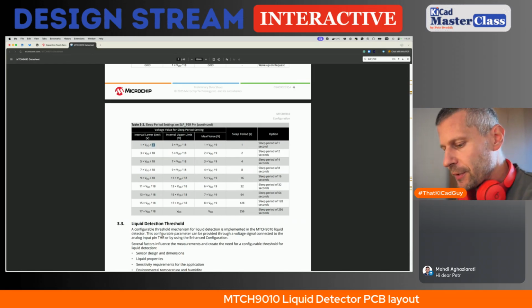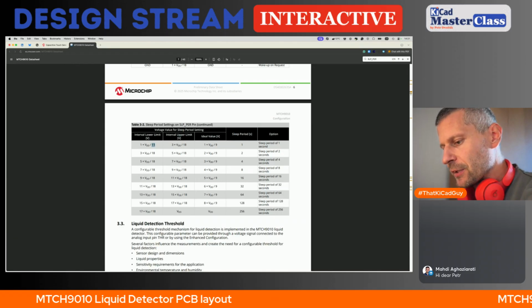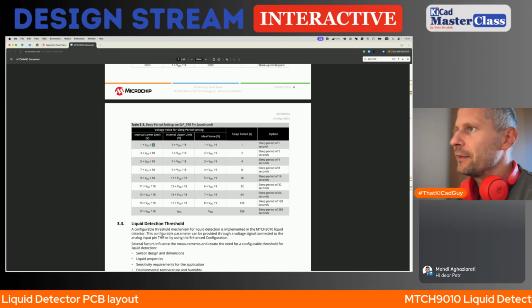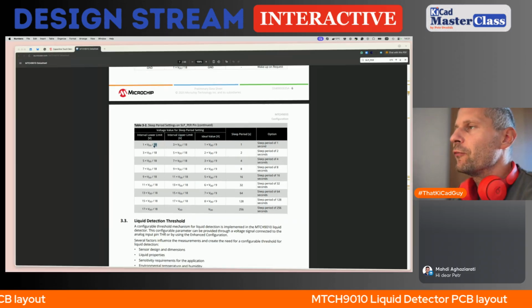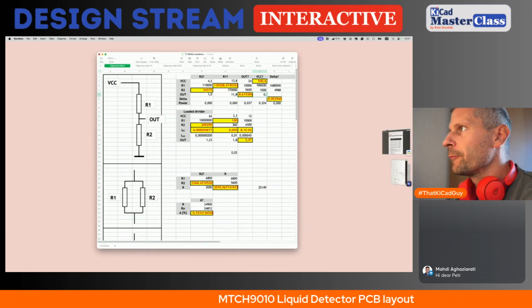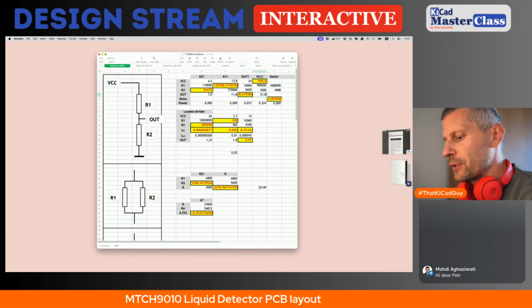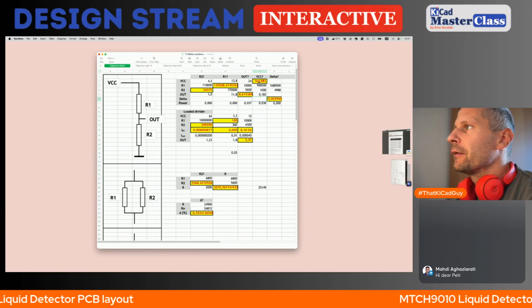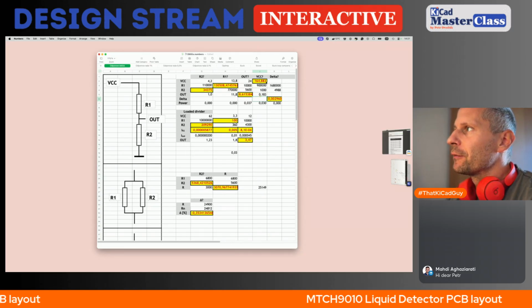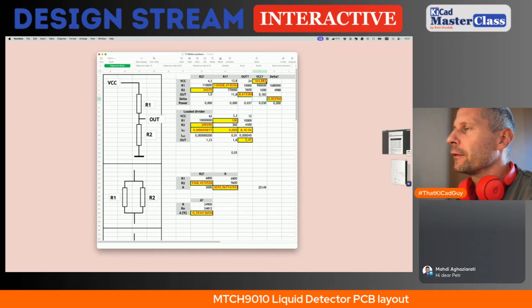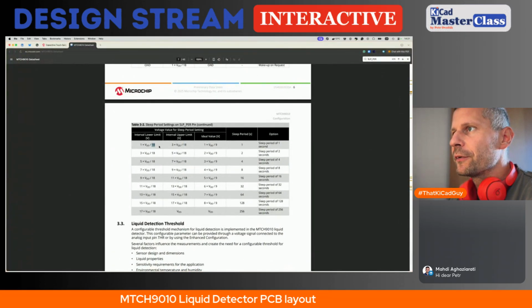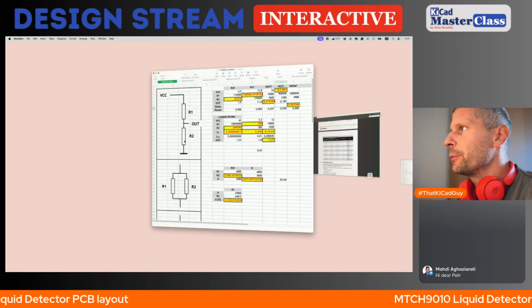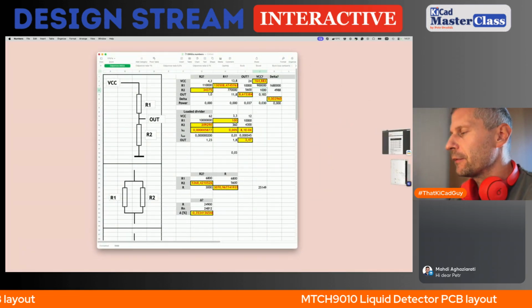The VDD is 3.3. 3.3 divided by 18 is 0.183 volt. So our maximum value is 0.183, yeah, definitely not right for our voltage. So we have to make the lower resistor bigger. Let's try 10 times bigger.